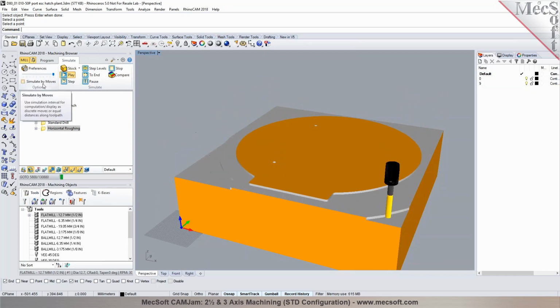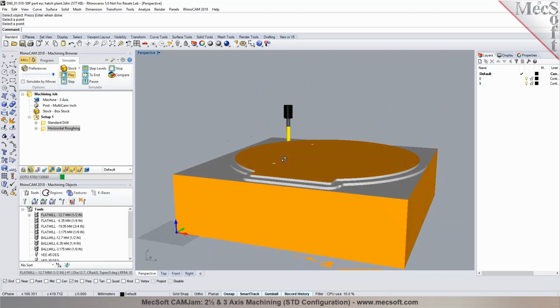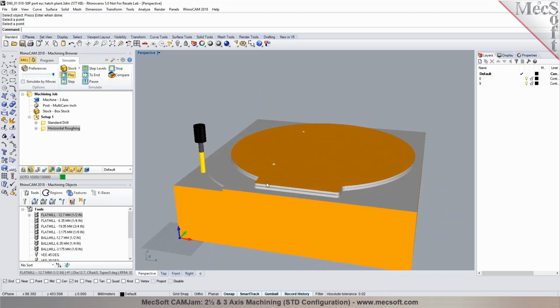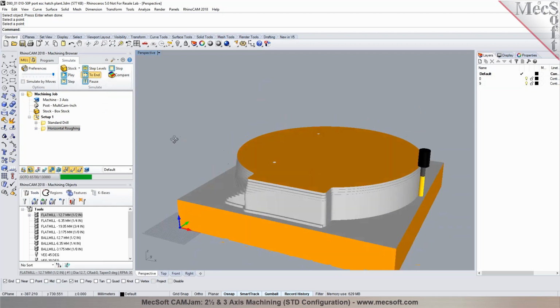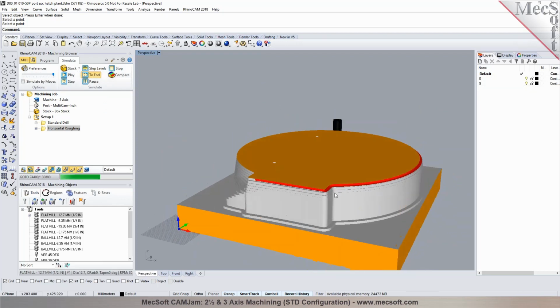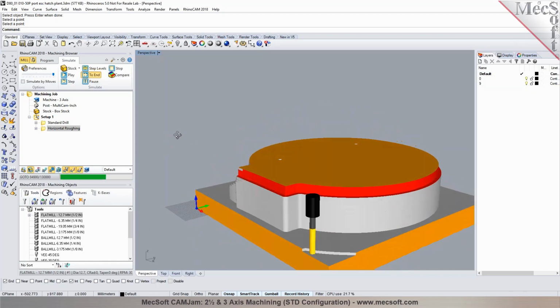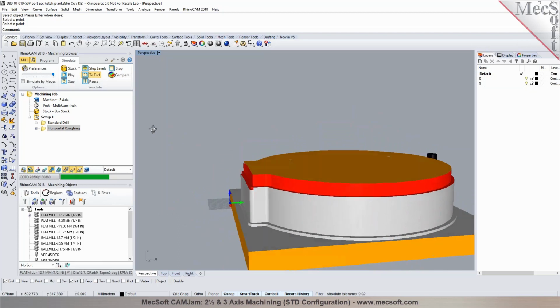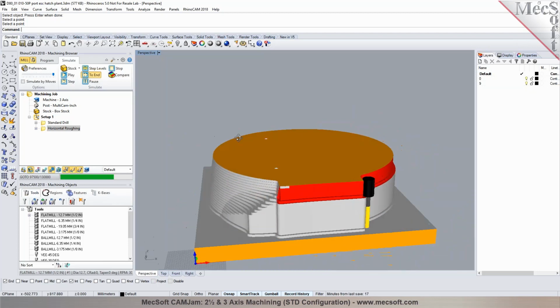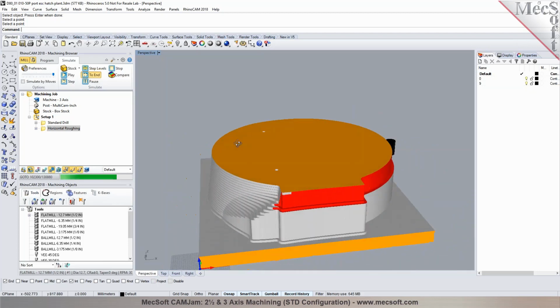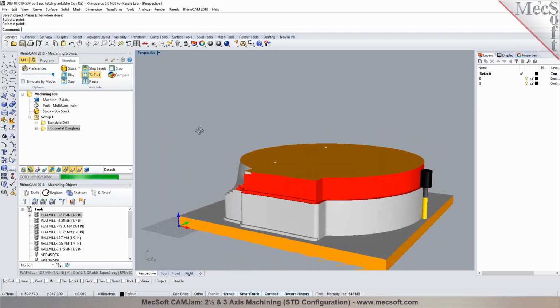I see. Now, if the tool is not long enough, the tool holder might collide with the part. You can actually view all of those in your simulation here. So if you do a simulate to end, it'll run through the simulation, and if there's a collision, it's going to mark those areas in the simulation. Okay, I see. The red areas are the collision. And that's where it's really helpful to make sure that you're accurate with your collet diameters and...